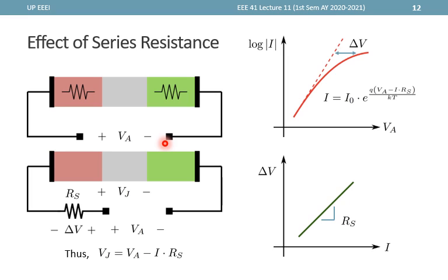the voltage, the slope of the current on a logarithmic axis should be related to q over kT, which is some constant slope. However, since there is some finite resistance at the quasi-neutral region, some of the voltage will be dropped across these resistances, which is no longer consistent with our assumed law of the junction, where we said that the voltage is dropped only at the depletion region.